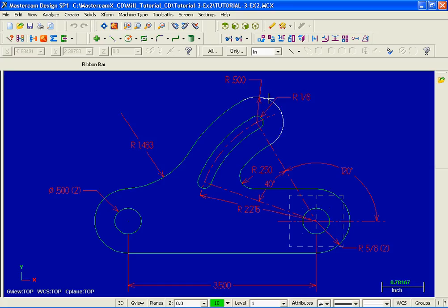Now moving up to the top of the drawing, we have an arc that has a radius of 0.5. Now when we create this arc, we're going to use polar coordinates to identify the center of this arc. We have an angle 120 degrees that we're going to use, and sliding over to the left we have a radius 2.215, which represents this center line that passes through the center of this arc. So we have a length and we also have an angle.